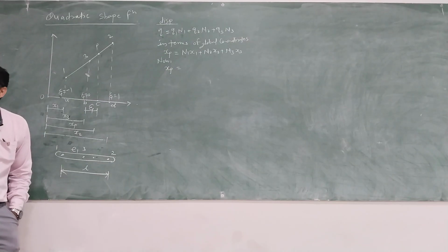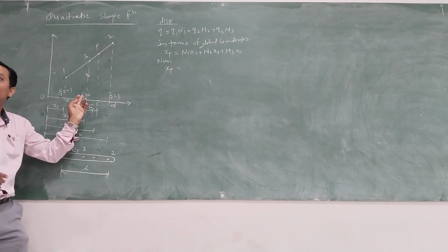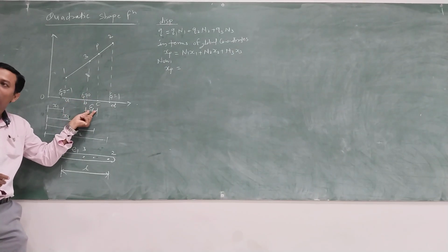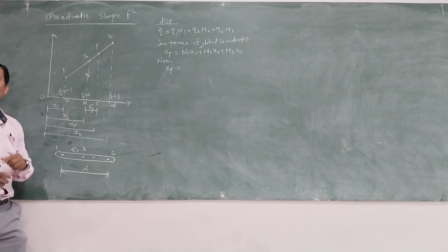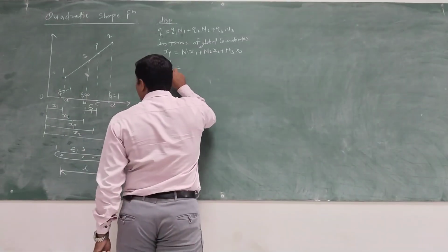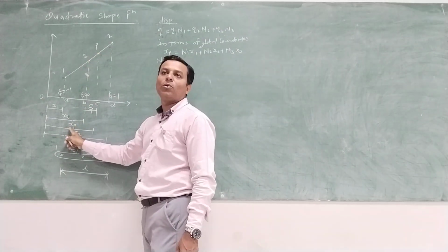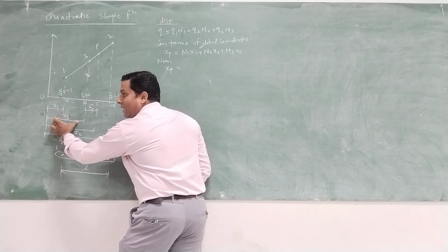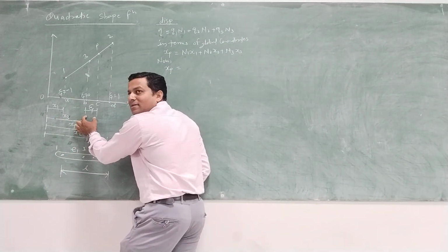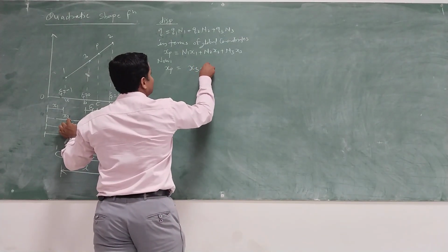Do you know the local coordinate for this point? No. You know the local coordinates for node 1, node 2 and node 3, so first we have to find zeta for this particular distance. So xp, the global coordinate of this intermediate point, is equal to x3 plus zeta.